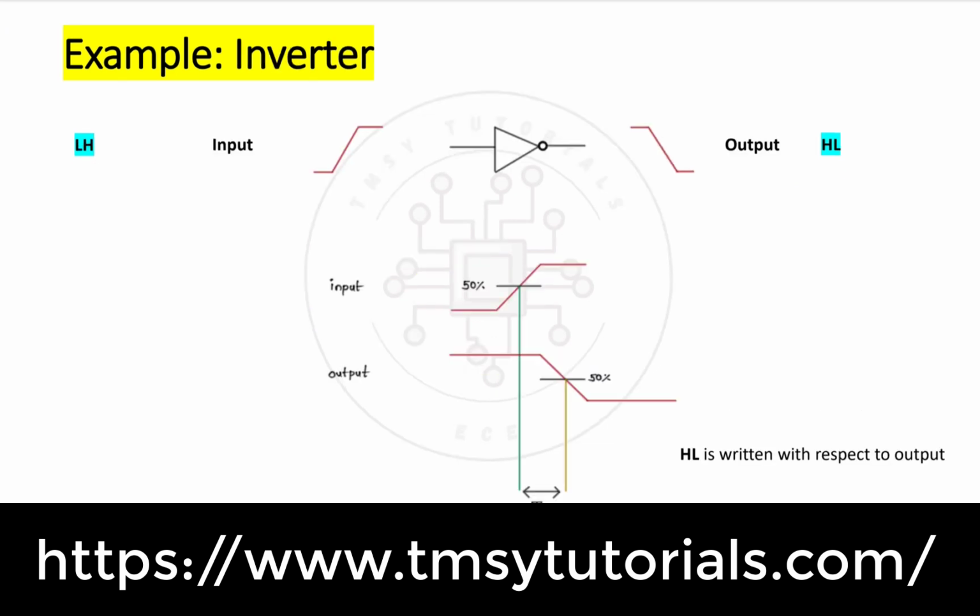Now let us take another example, an inverter. We know that for an inverter, when the input is 0, the output will be 1, and whenever the input is 1, the output will be 0. So whenever the input is going from low to high, the output is coming from high to low, that is the reverse of it. Input low to high, output high to low. Same here, we see in the waveform, input going from low to high, output coming from high to low. And this 50% we are taking, because we mention this particular percentage value in the .lib.